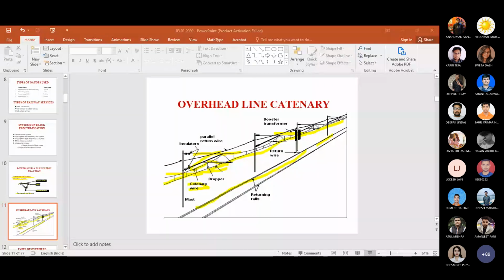That armature field interacts with your main magnetic field. You get a resultant flux line, and your motor follows it and starts rotating. After rotation, there is cutting of flux, and that rate of change of cutting flux causes the induced EMF. That's the basic idea.